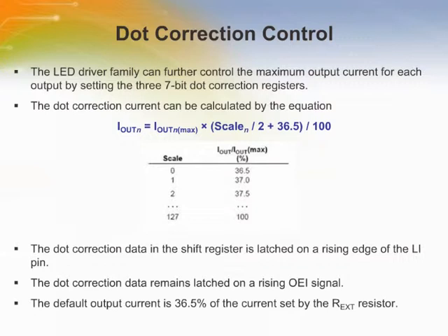This feature is useful because not every type of LED, red, green, or blue for example, has the same level of brightness for a given current, and the brightness could be different even from LED to LED of the same type. By scaling the output currents so that all the LEDs have matched intensities, the application will have full color depth when using the PWM counters.